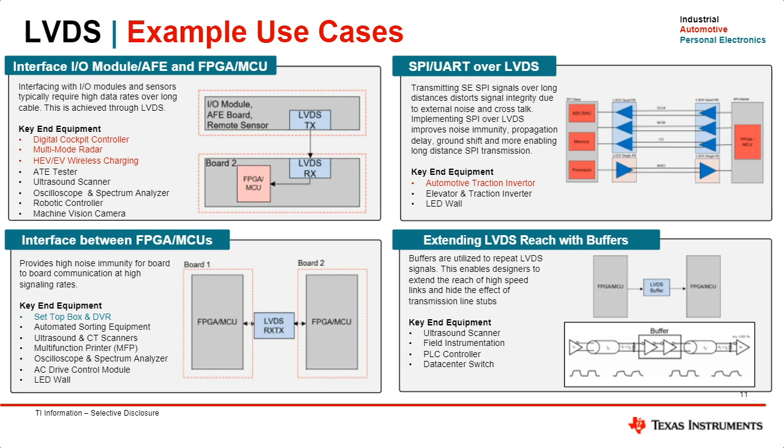And so the concern with this is transmitting this over single-ended SPI signals will have those drawbacks I discussed before. What we can actually do is implement each lane of SPI to differential LVDS using LVDS drivers and receivers. This will allow for ground potential differences between the two devices. It will also allow for much greater signal integrity during transmission.